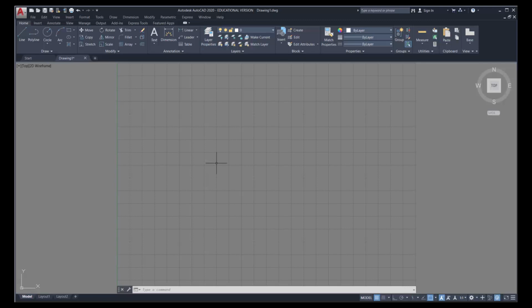So what has changed in our drawing? In the layer menu, if we now go to the top, there's a little arrow that points to the right beside layer 0. If I click on that, I now see the layers that I've created, and this allows me for easy control of which layer I'm going to be working in. Now the basics with this is that the layers are affecting whatever you draw new.